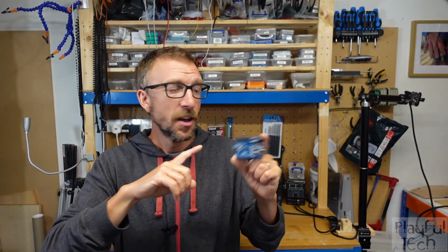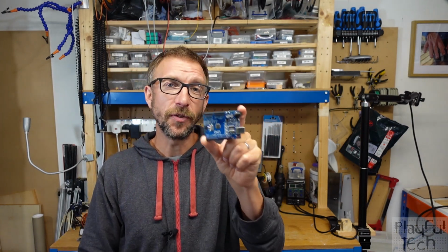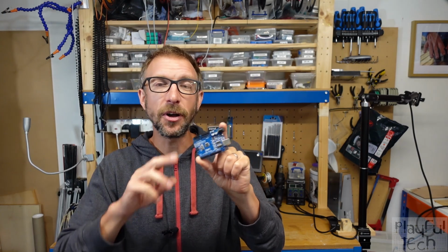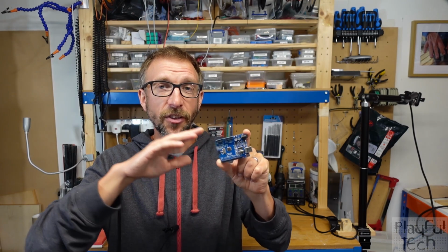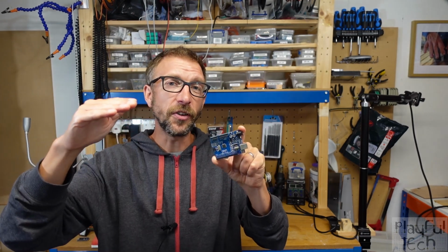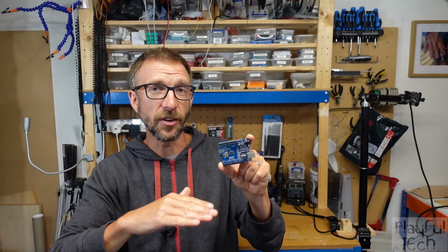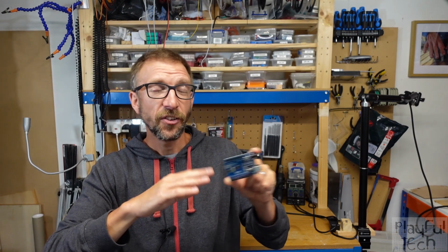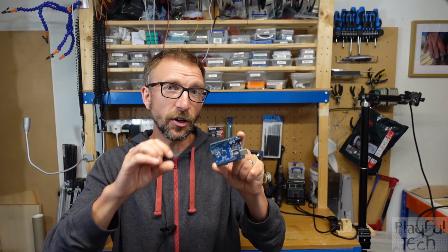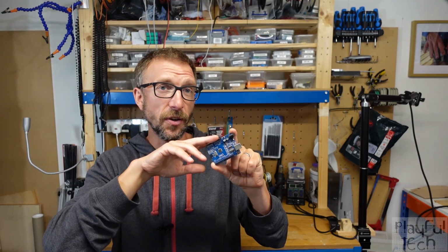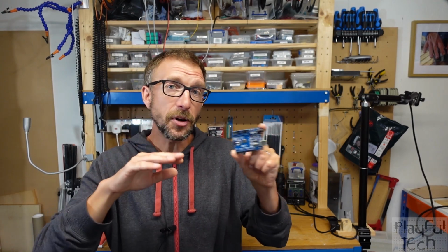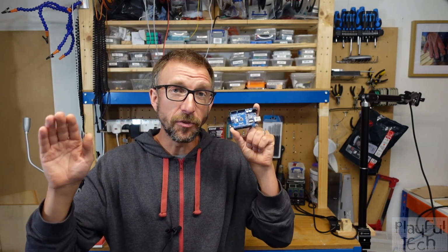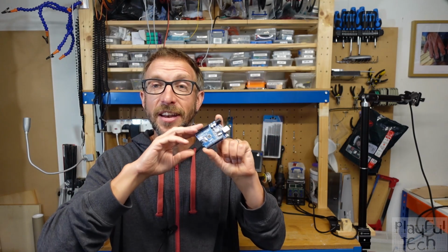So suppose you have a 5-volt output device like this, but then you apply PWM with a 75% duty cycle. So that means it spends 75% of its time in the high state and 25% in the low state. So that's going to give you an average voltage of 75% of 5 volts, which is 3.75 volts. And by adjusting the PWM duty cycle to range between 0 and 100%, that's how you could dim an LED light, for example.